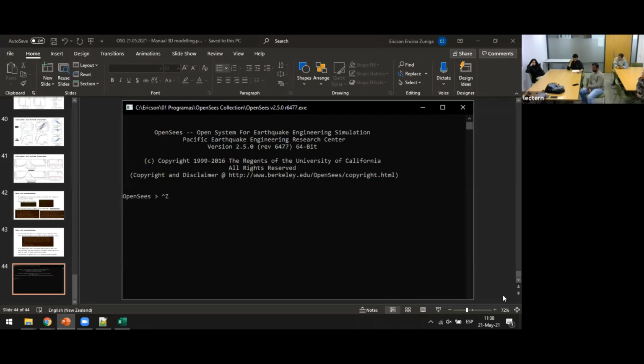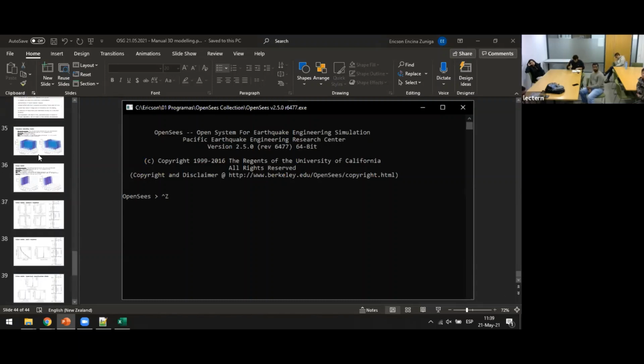Oh, okay, got it. But the problem is that you don't have the top flange with topping and web together. So it's more flexible than this one, because this one has a larger section. And that's one of the limitations, but that's why I pointed out that all the models are centerline models. Okay. So for each web of the double T's for the floor, you had the line element and then the shell. Exactly. Thank you.